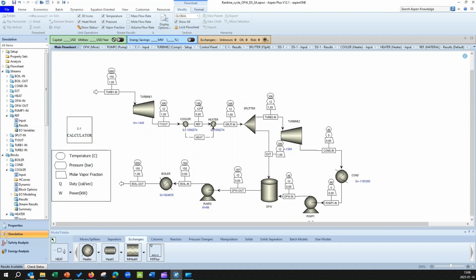But what I try to say is that when you change this discharge pressure, then the program automatically can read the value of saturation from this stream, and that's the trick that we want to do. Now let's continue and see how we can modify the design spec in order to get the proper settings.